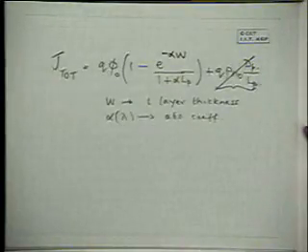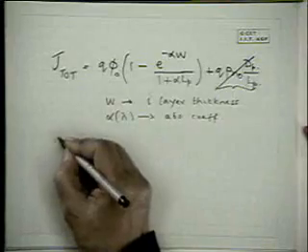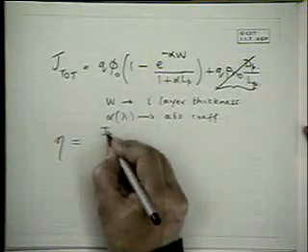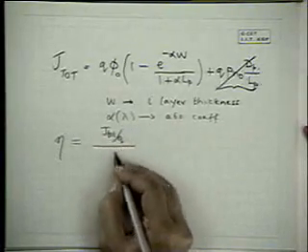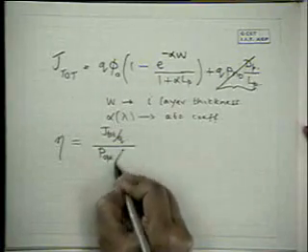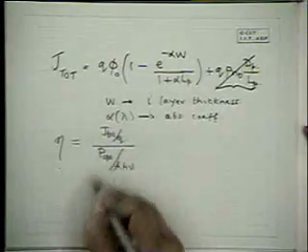So as a result, we find that under normal operating conditions, what is the quantum efficiency? This is just J tot by Q, that's the number of electrons, divided by the number of photons, that is P opt by A h nu per unit area.